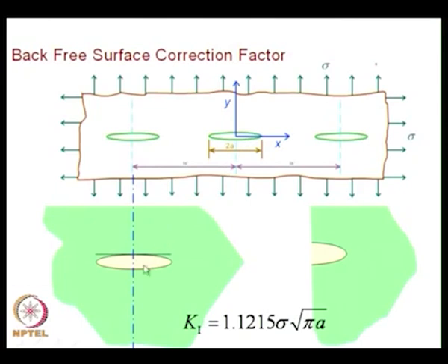What you will have to note here is, when you cut like this embedding the central crack, because of symmetry the slope will remain horizontal, but if I cut along the center of the crack, which is the case in a single edge notched specimen or double edge notched specimens, you will have a higher stress intensity factor and the crack will open up more.